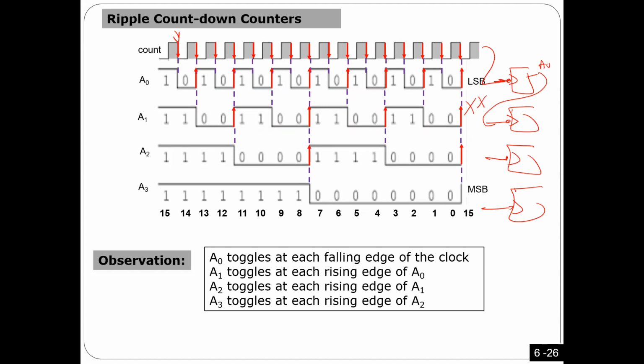You know what I can do? Very simple trick. I'm not gonna connect it to E0. I'm gonna connect it to E0 prime here. So this one should be okay. That means this one here is not gonna be triggered by E0. It's gonna be triggered by E0 prime. And in E0 prime, every rising is gonna be falling, because remember, every flip-flop is gonna give you E0 and E0 prime, the complement of this one.